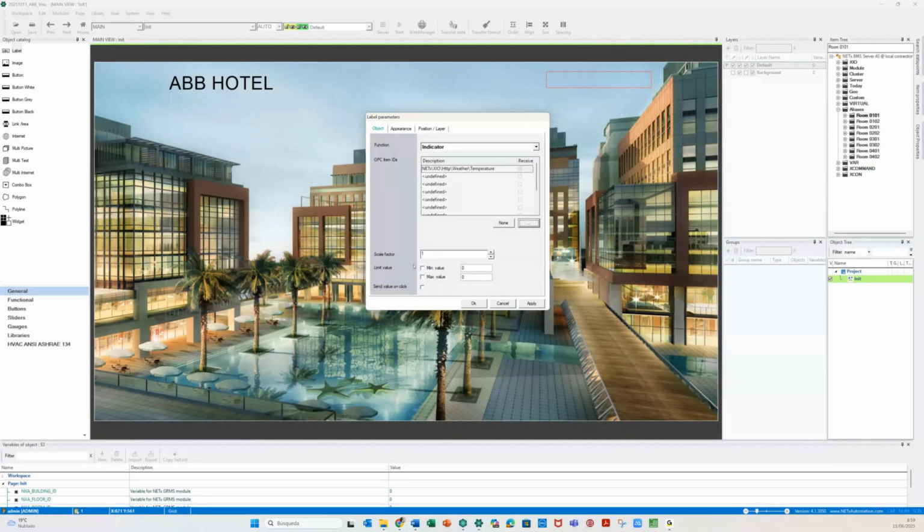But maybe I can say, okay, if the value is higher than 21, it is out of my limits, for example, or less than 0. So the tag will be a different way. Instead of transparent and in black color, it will be a red. The rectangle will be red, and with yellow color the text, for example. So you can define limits for this.